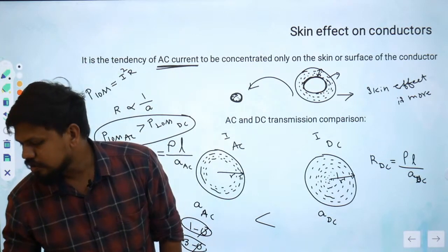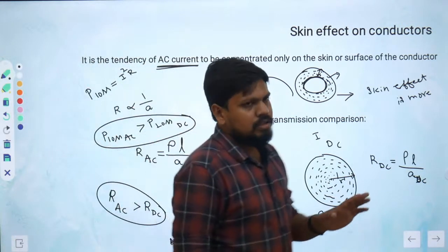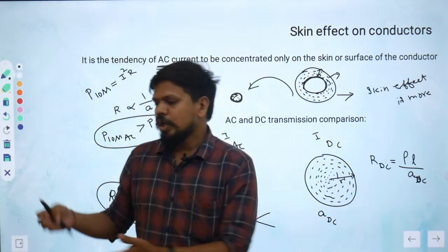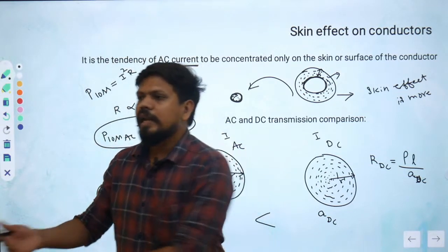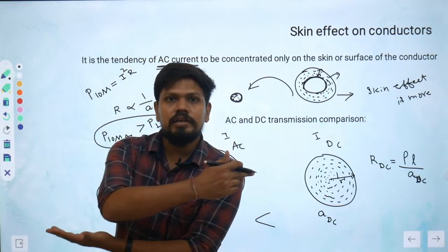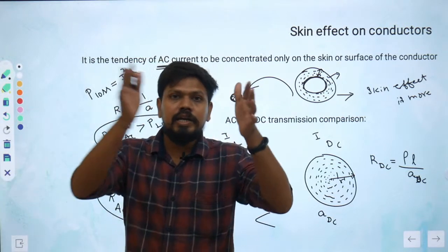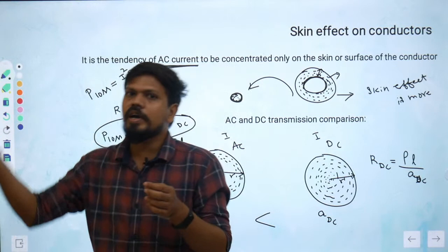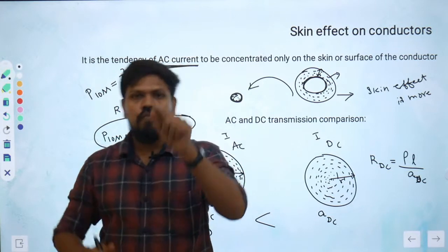If you have any doubt, sir, about voltage step up transformer, power step up, yeah. If you ask me what is after generation, I will give you a clear cut idea. For example, we have a thermal power plant or hydroelectric power plant. 11 kV voltage generation will be there. Directly 11 kV will not be transmitted, right? So we will step up that voltage to 400 kV, where you can connect to a power grid. The power grid voltage is 400 kV, so we will be stepping up that voltage immediately after the generation.